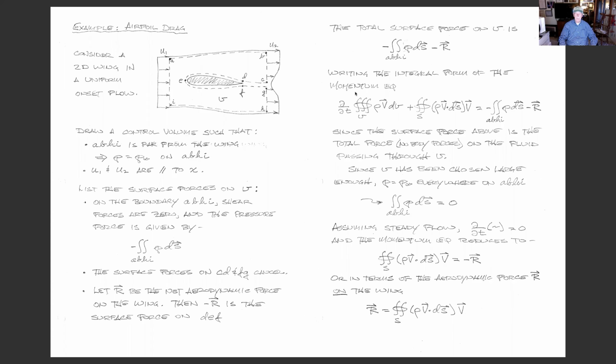Why is that? Because they're little to begin with. Square cube law is, if you scale something up, areas go up by the square of the length scale, volume and hence mass goes up by the cube of the length scale. And that's why an elephant has great, big, thick legs, because it's walking on them.